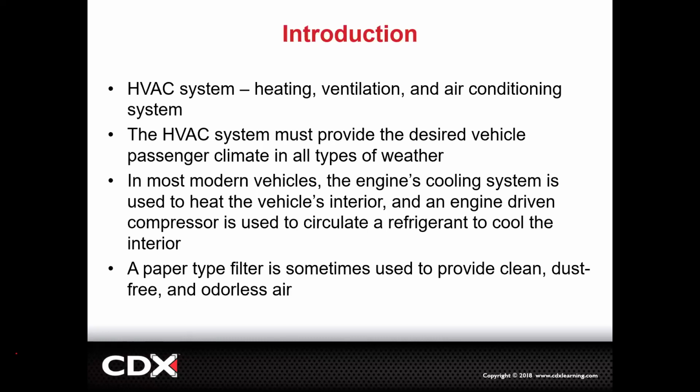If you have a vehicle that's blowing not hot enough heat, you may be looking at the fan running too much. You may be looking at the thermostat stuck open. You may be looking at a coolant leak, right? So it's the same parts, just from the other perspective, and we're looking at them in a little bit of a different way.